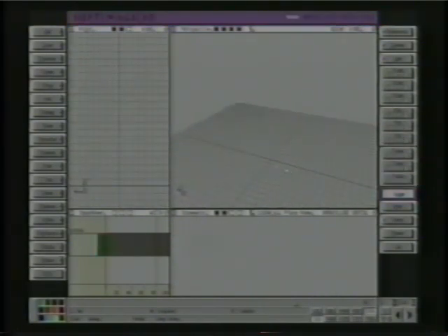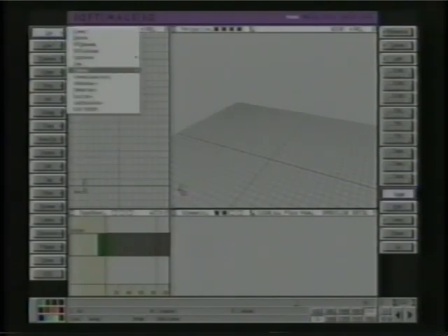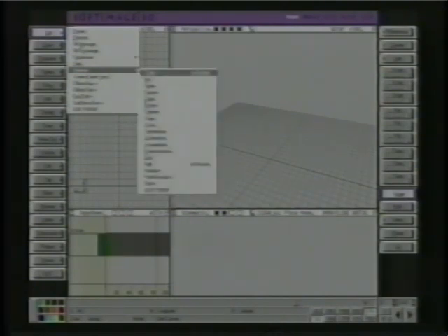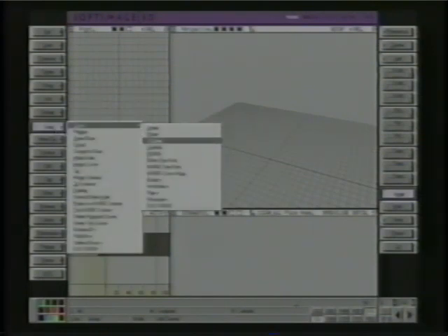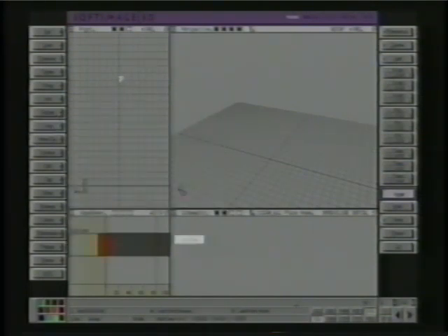Another alternative to plain old skinning would be to use guided extrude. It's quite a powerful little feature. It doesn't work with relational modeling, but otherwise it's very nice. Well, let's start off by drawing a B-spline curve. You don't want to use NURBS with this because it doesn't work well with NURBS.